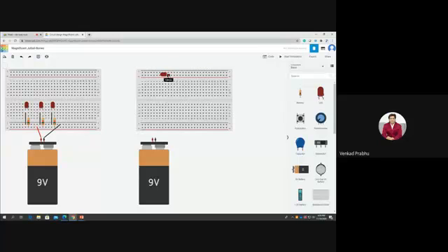Why? Because if you move your mouse to the LED leg, this is actually the cathode leg, but this cathode leg is in the positive. Cathode is negative actually. So this should not be like this. And this leg is an anode. Anode is positive actually, but we have inserted it in the negative. So just choose this, rotate, and place like this. This is the correct way of doing it in the outer part: cathode in negative and anode in positive.